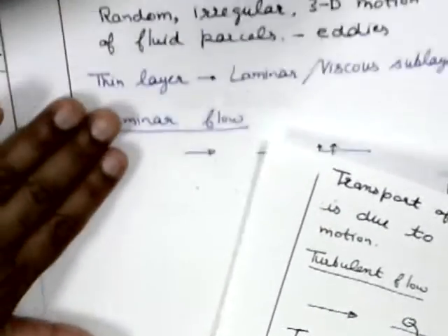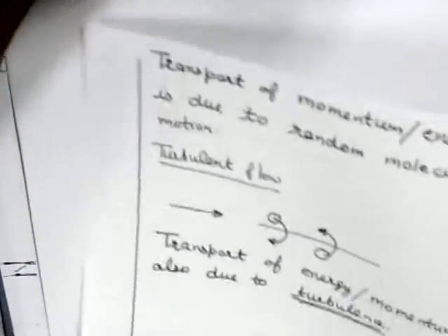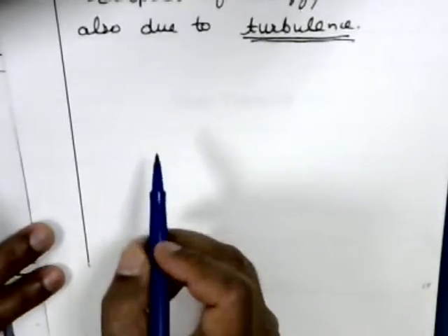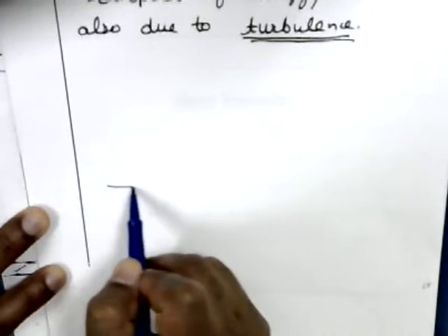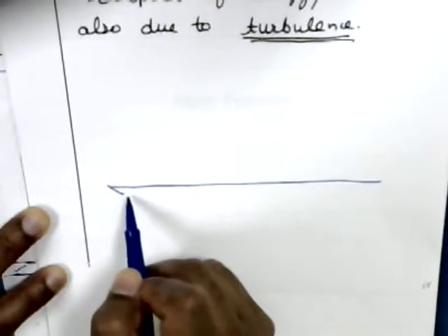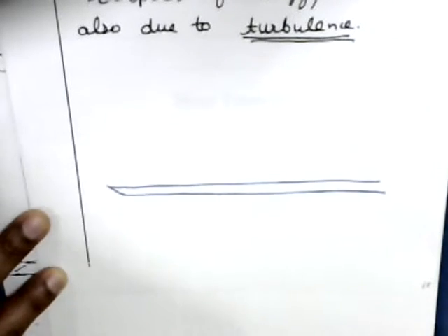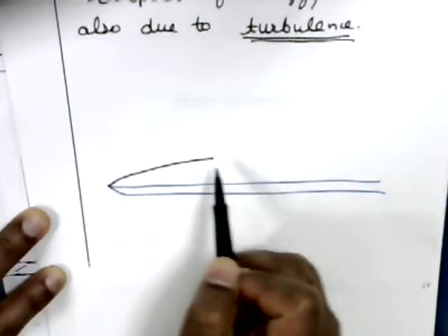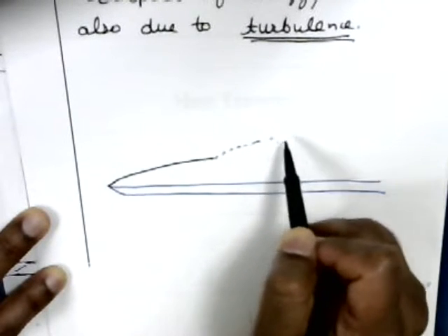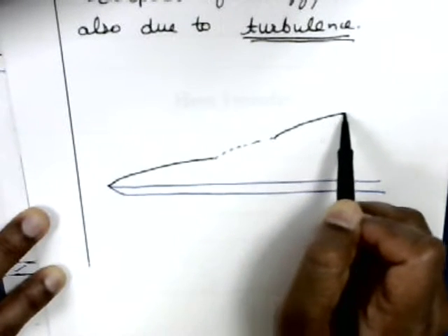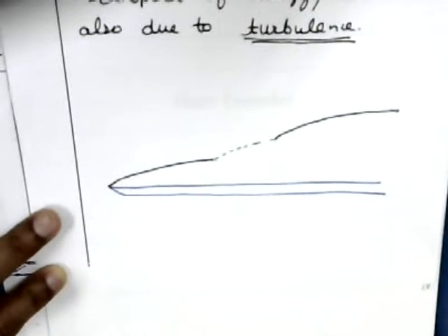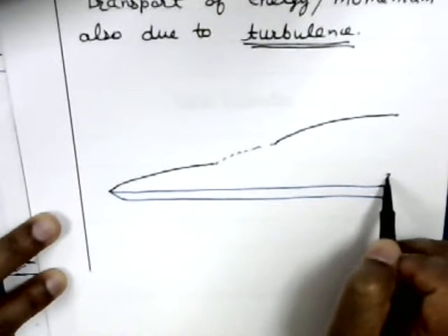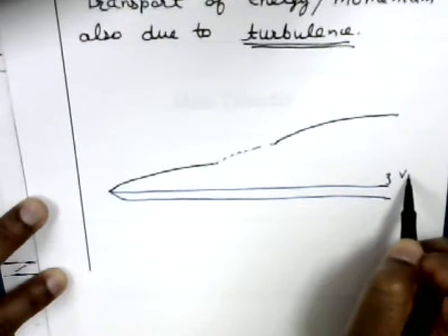And so let me again draw the boundary layer, and in the turbulent region, so a flat plate. So the boundary layer is laminar up to a certain point, then there is transition and it becomes fully turbulent beyond this point. And in the turbulent region, there is a region close to the wall, we call that the viscous sublayer.